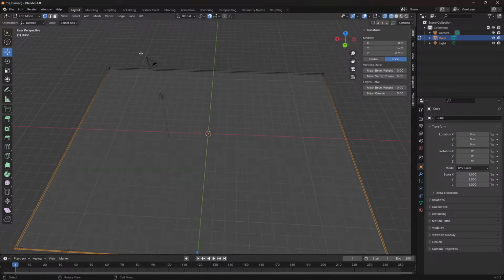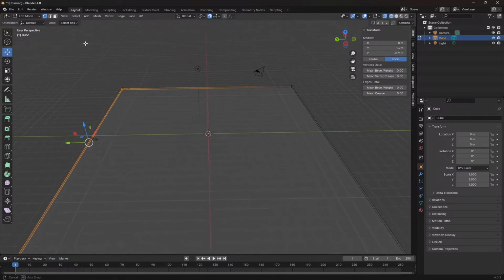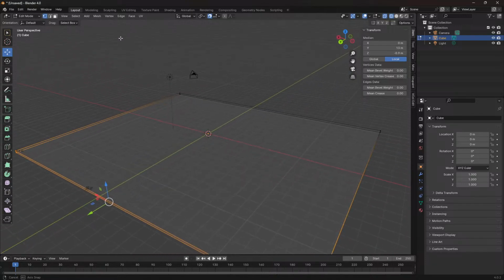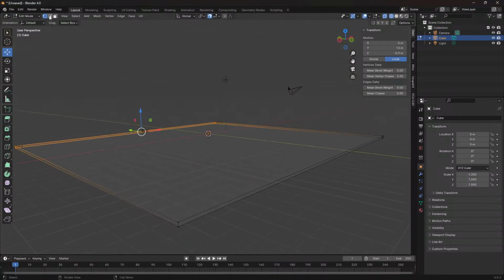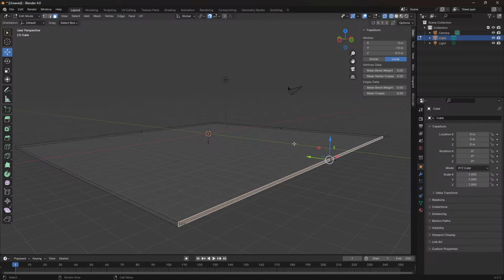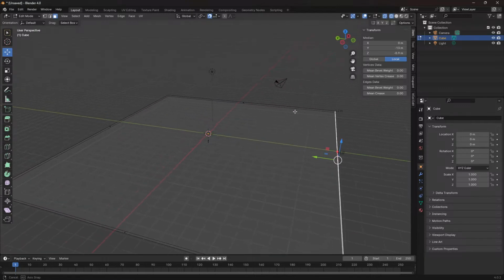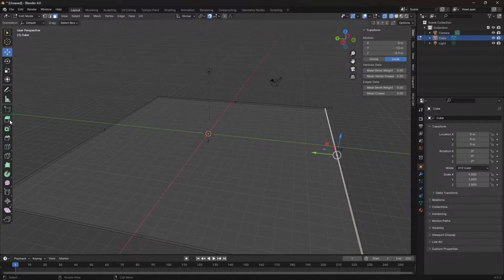Enter. Now, you may be asking why I did 13 on those sides. And there's a reason for that. What I'm going to be doing is I'm going to go to faces. I'm going to click on this dot here, and I'm going to do an extrude.